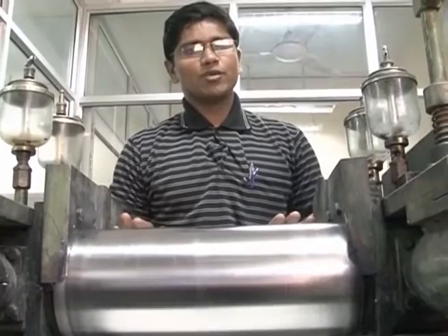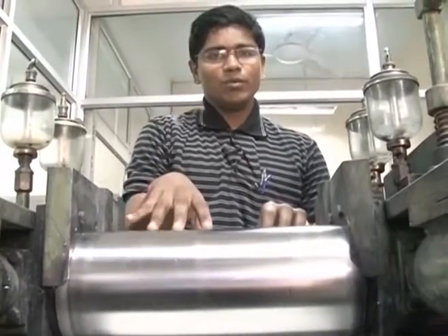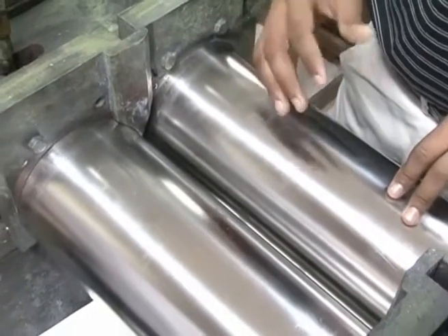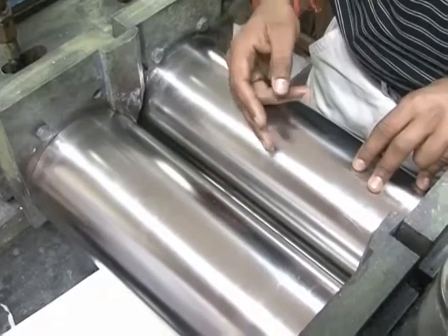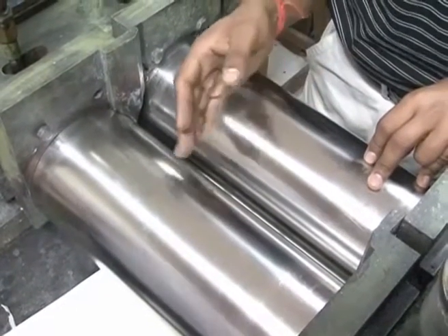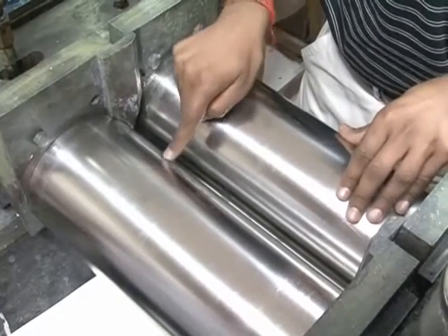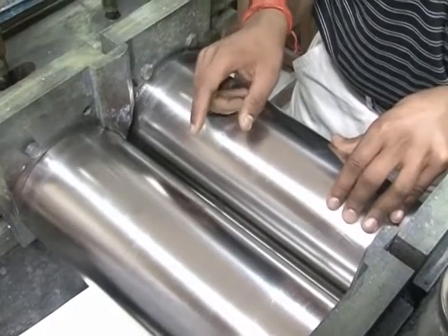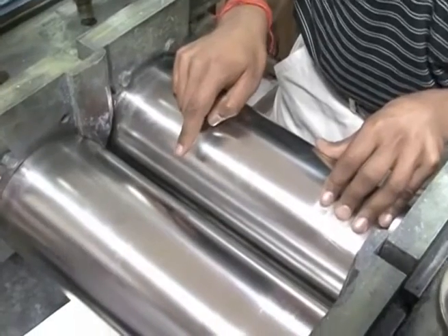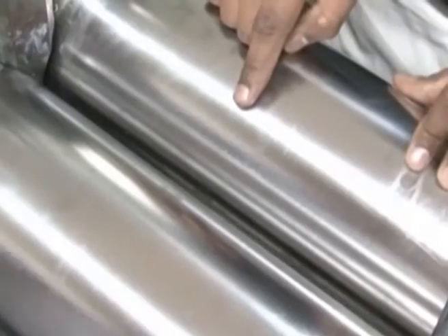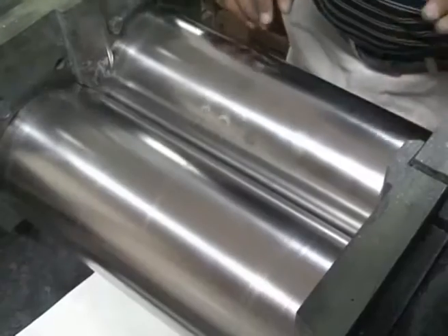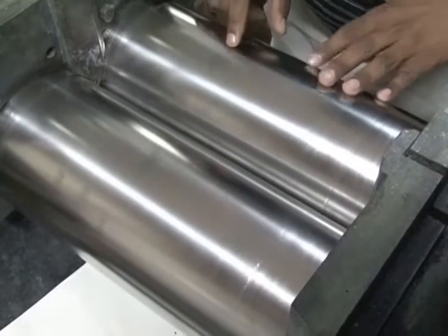This is the two-roll mill where we fabricate the polymer rheological abrasive medium by mixing with a two-roll. In this, one roller is the supporting roller and one roller is the grabbing roller. Once you are processing the medium, the medium will stick to the one roll and another roll supports in rolling. The gap between two rolls is called the nip, and this is a variable. You can vary the gap. Now you can see the variation in the gap. Depending on how much gap you want, you can set the gap. Now you can see the motion of the rollers.